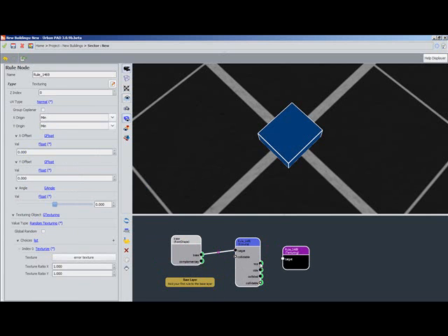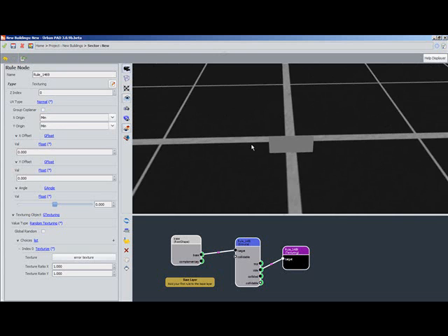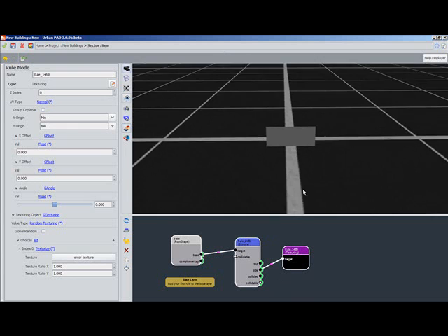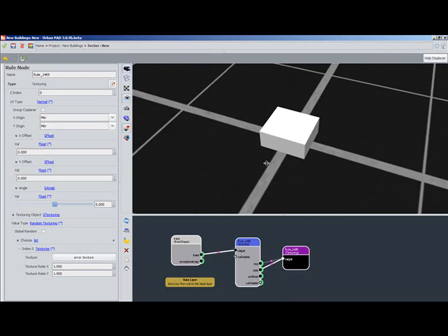I've added a texture rule. I'm going to texture the bottom part of this building. Right now we're in layer view, so we can see exactly what we're doing. When I go to expanded view, I don't see the entire cube. This is because untextured polygons in UrbanPAD will not be displayed on screen. So I'm just going to take my top output slot and put it into the texture node so that everything's displayed.